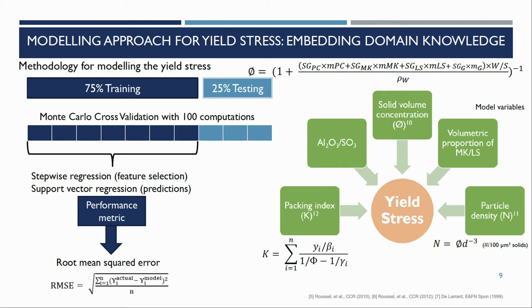There are simpler models that we actually start with that are based on linear regression, and that would literally just be yield stress equals a coefficient times k, plus a coefficient times that ratio, plus a coefficient times that ratio, plus a coefficient times the solid volume concentration, et cetera. So this winds up not being just a linear function. There's an additional transformation that the algorithm is doing, but once all the parameters and hyperparameters have been set, then the model is static.